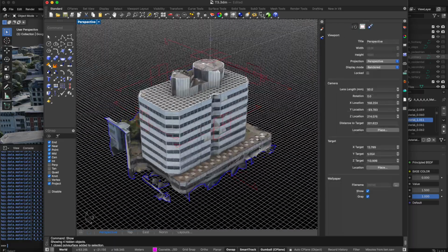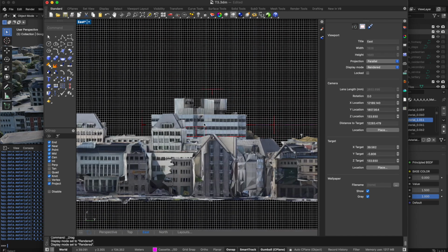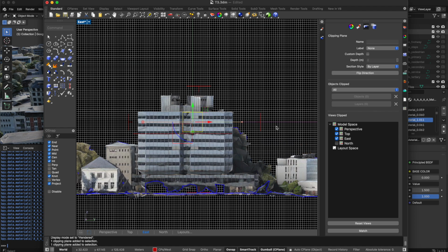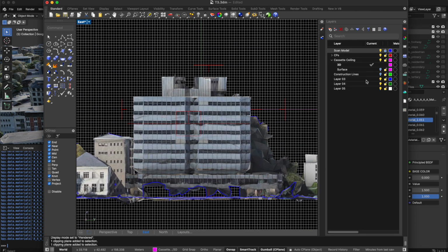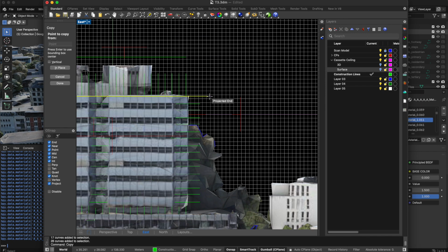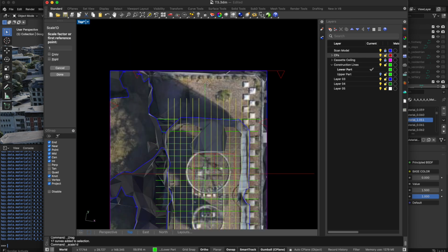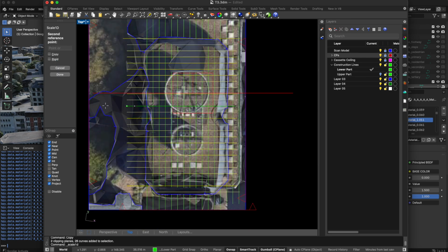Okay, then I go to a side view and create the grid for the lower part. I can base it on the upper part grid and just copy it down. Then I extend it by using the commands scale 1D and array.